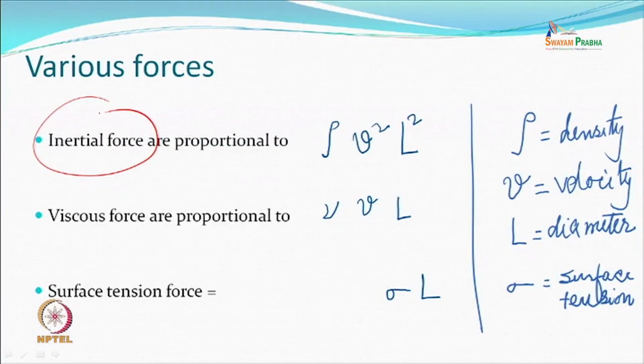Other is because of that also, plus the forces that you apply, which are like the inertial forces, are going to be governed by some of these numbers. So velocity obviously is to the square, the power 2. The diameter also is like this, and therefore the force that is generated or to be generated will be always higher. The viscous forces are proportional to the viscosity and the velocity and the dia.